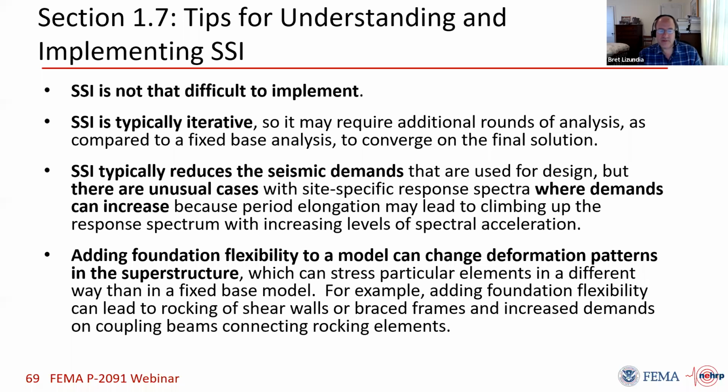A big thing is that adding in that flexibility can really change the way things move. I showed you that example on the opening slide, and then that worked example that we had done in the ASCE 41 design guide, where the brace frame converted from one mode to a totally different failure mode, depending on whether we did or didn't have foundation flexibility. It doesn't always happen like that, but it's something to be aware of. There are situations with these concentrated shear walls or brace frames where that can be particularly true, and important, because you may be misleading yourself about what's really happening if you're just doing a fixed base analysis.